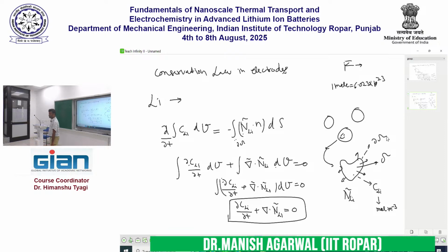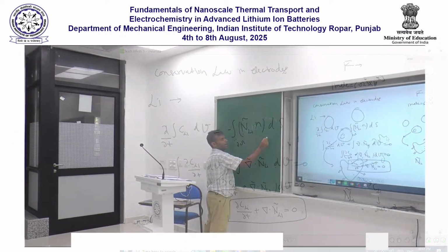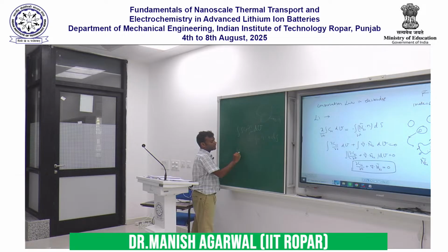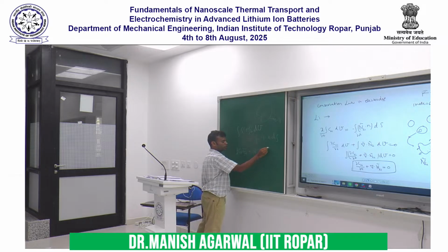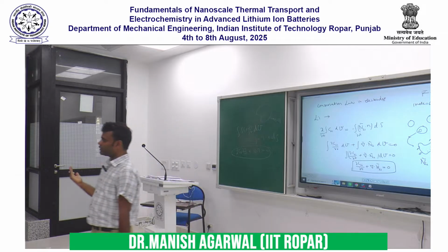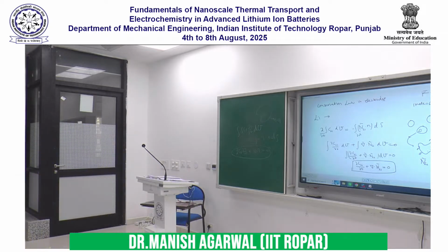That is the heat changing in the total domain, and I can equate it to minus q dot n dS and do the same steps. Ultimately I get rho Cp del T over del t plus del dot q equal to 0, which is the heat equation. So this particular form is very common. If you derive mass conservation, again you will have the same kind of form.